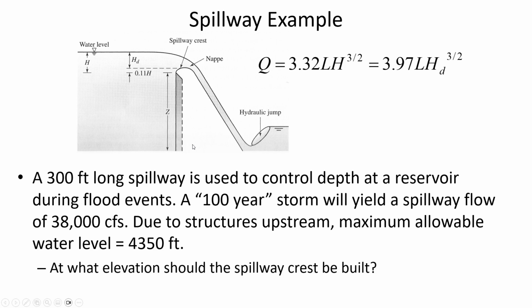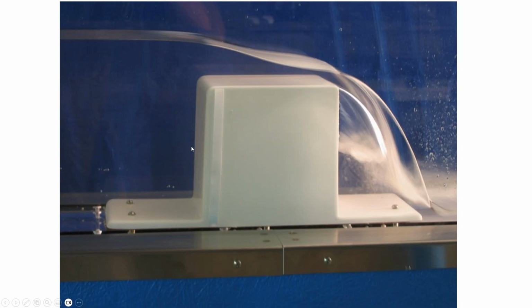So that's a spillway, and the video that we watched just talked about weirs in general. And this gives you an idea that as the water is flowing over an obstruction, there's actually not just a single depth. You know, we talked about how when an obstruction gets progressively deeper and deeper, the water flows at the critical depth over the obstruction. But there's multiple things happening in a weir this short, because not only is the water going to be flowing at the critical depth over the obstruction, but then also the water is being drawn down as it flows over the edge of the weir.